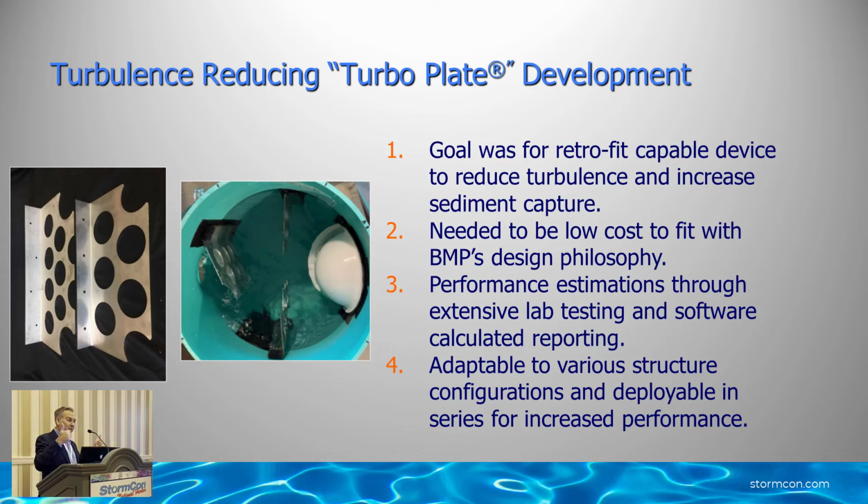He's down in our booth, so if you like the turbo plate, give Matt a big thumbs up. But we just ran countless experiments. We moved plates, we changed them, we changed the size of the perforations. The initial plate was a solid plate. We tried a perforated plate. Solid plate worked better.